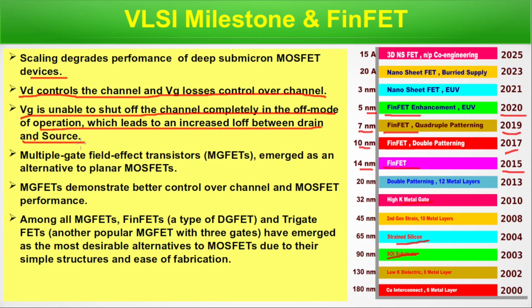When drain voltage is applied, there is a field, so it has an area of impact for short channel devices. When source and drain are coming closer, the source junction area comes almost under the control of the drain voltage. Like this. Here it's drain. From this it actually controls this zone, and as a result, the barrier gets lowered here.